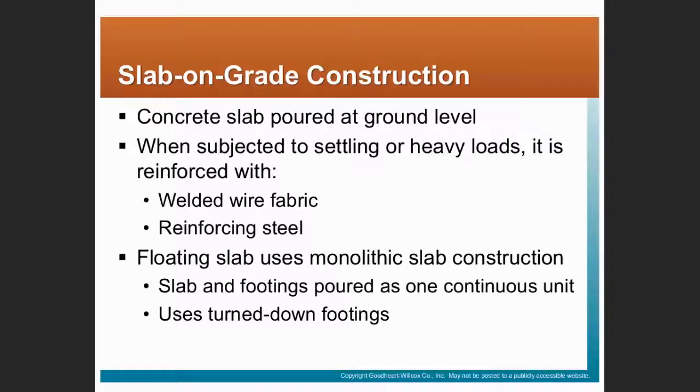So they don't remove any of the soil first? No, for pile driving, it's basically brute force, right? In the auger cast pile or the caissons, we are removing soil and then putting something in. In the case of pile driving, we are driving something through the soil.